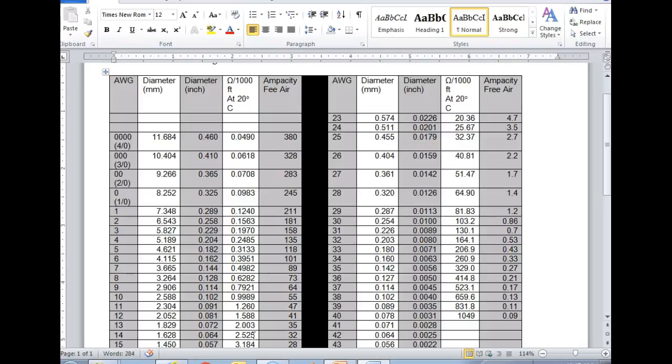The wire would drop 50 volts. That means if I was trying to run 2,000 feet of 14 gauge wire and hook up a light out here or hook up a load out here that required 10 amps, then I'm only going to get 70 volts out there. And it's not going to do near the work because power varies with the square, right? Y'all understand that? So just because you halve the voltage to a device, the work that it does is going to drop down to 1/4.